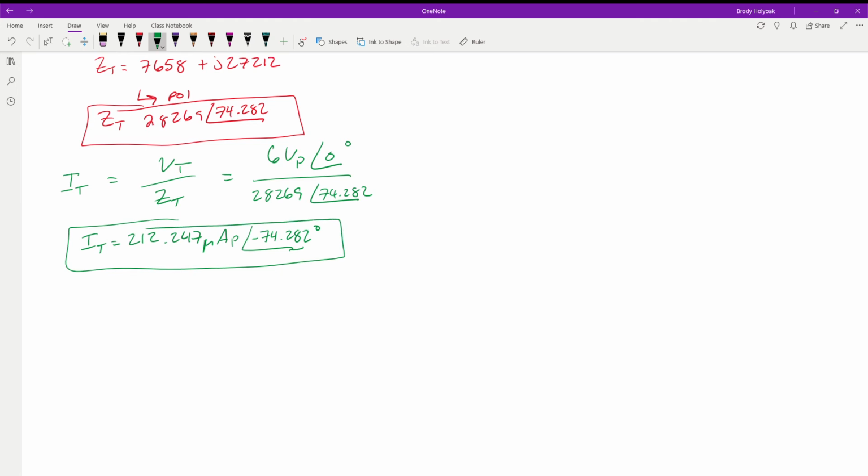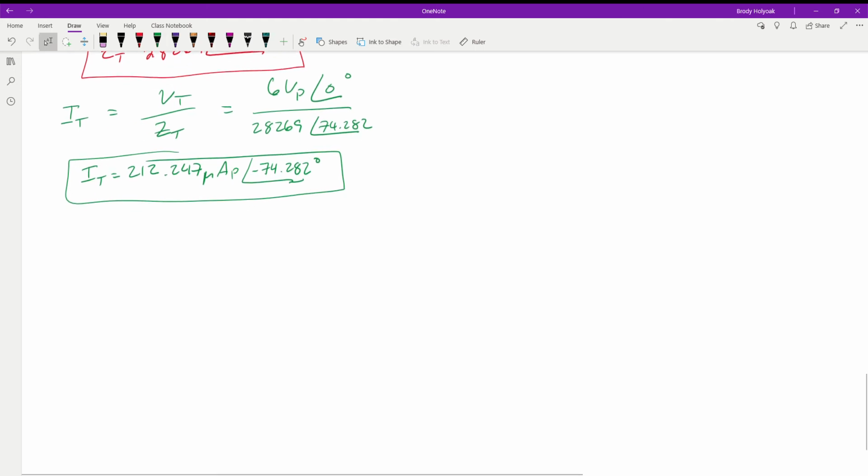Now that we have those, we're going to continue on using that value. We're going to solve for the voltage drops across R1 and L1, and then get our voltage drop across VB, so that we can continue on and find the currents through the individual branches and their individual voltages. So now we take VR1. The current going through it is I total multiplied by resistance 1.